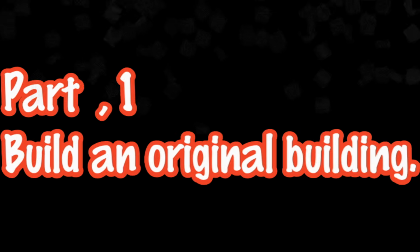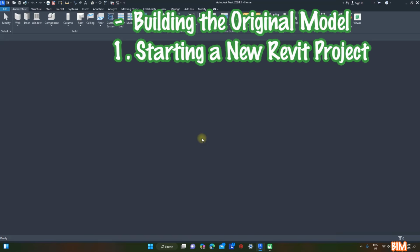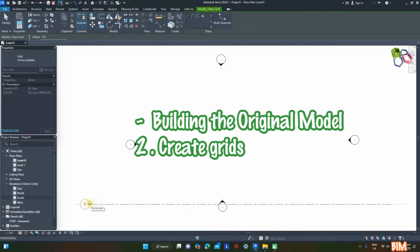Let's start to build the model step by step. Part 1. Building the original model. 1. Starting a new Revit project. Open Revit and start a new project using the metric architectural template.